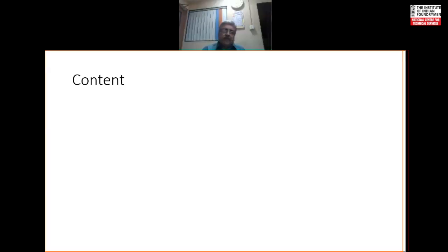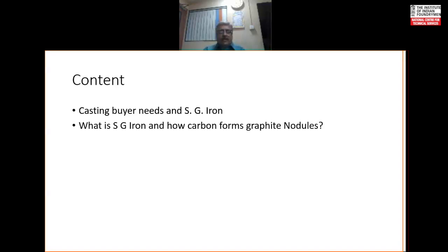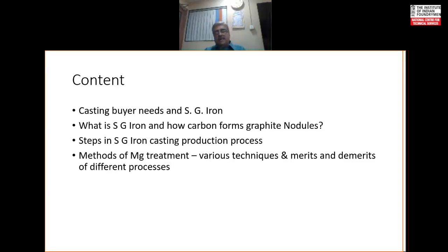Thank you. What we will cover today is, we will once again revisit why people buy castings and then go towards SG iron, understand what is SG iron and how carbon forms into graphite nodules. Then we will go to the steps in SG iron casting production process. Then magnesium treatment is one of the keys for getting spheroids. So what are the different techniques that are used for doing the magnesium treatment and merits and demerits of these different processes.